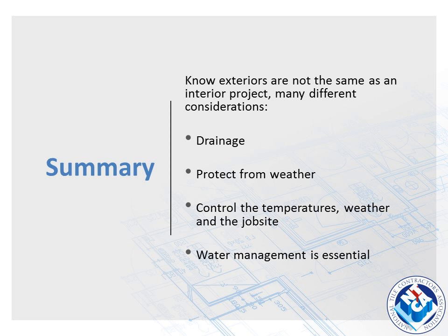If the flashing's not lower than the membrane, the waterproof membrane, it's not going to drain. It's going to accumulate right there at the edge of the deck. Keep those things in mind. Protect the installation from weather. Don't install in bad conditions. Try and keep the control of the temperatures and the weather and the job site as much as possible. Water management is essential. You've got to keep water out of an exterior installation or you are going to have all kinds of discoloration, whether it's efflorescence, latex leaching, or for that matter, if poor coverage, you're going to have a failure. It's just going to start popping off the wall.